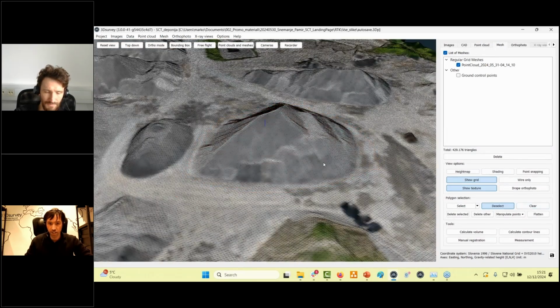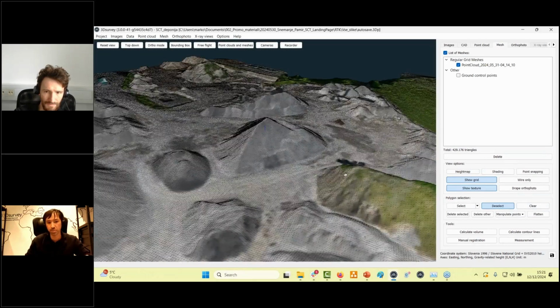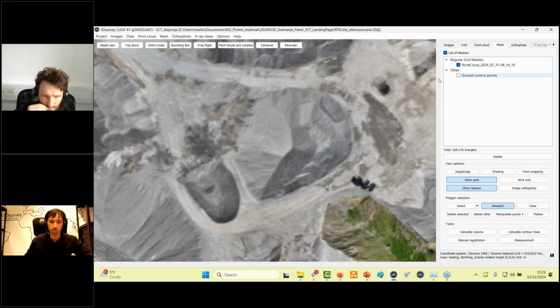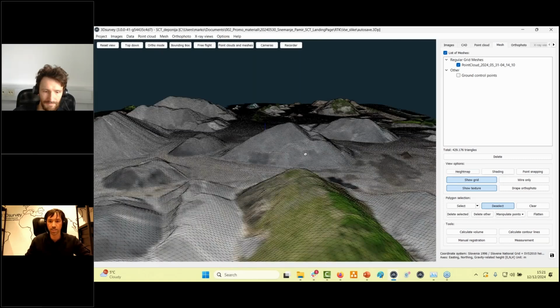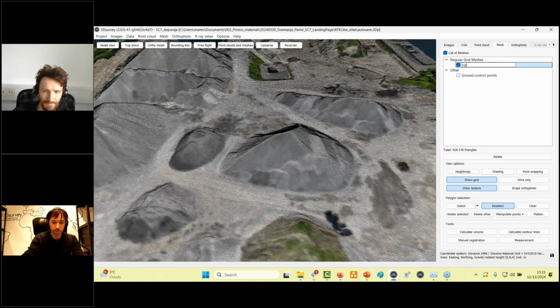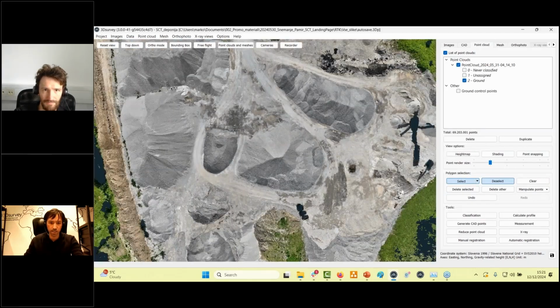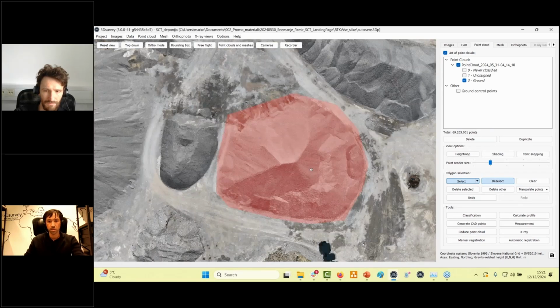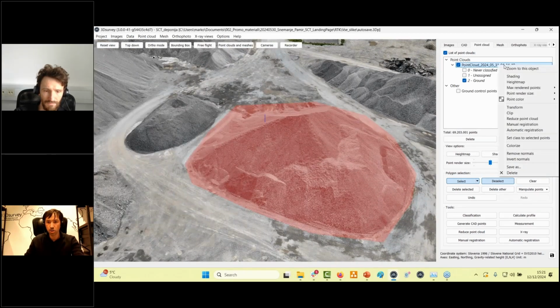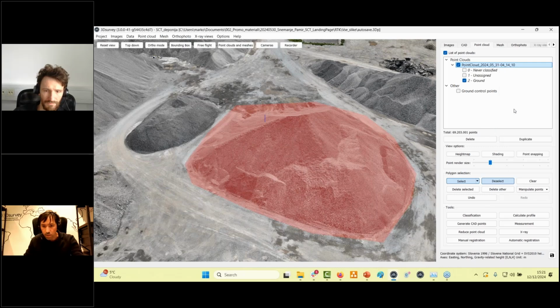Let's clear the selection and show you the second approach of the same scenario. So let's say here we have our first surface. I can rename it. I can go back, and the same way I selected before, I select this on the point cloud. Before I delete this, I will duplicate my point cloud. So I right mouse click on the point cloud, and select, oh, not actually right, but I have here the duplicate function.